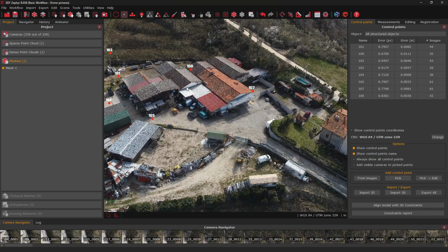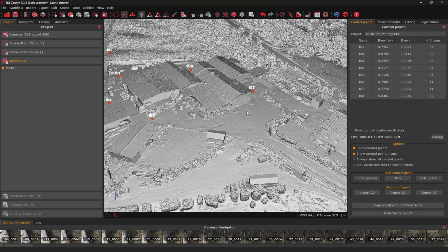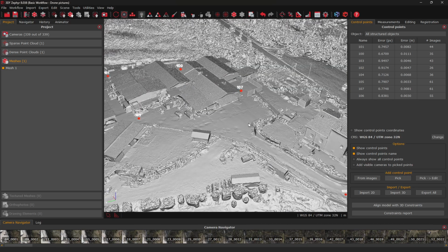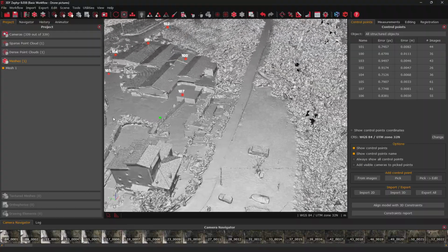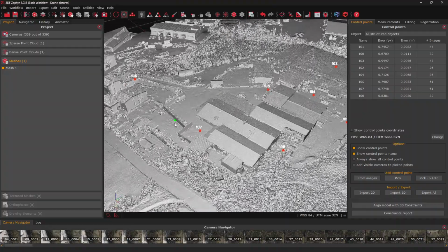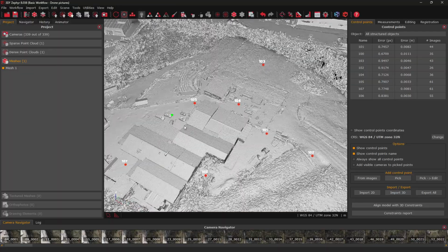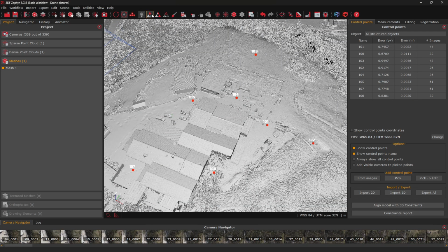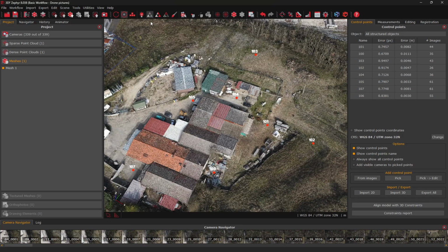To check the surface geometry details, enable lighting in the workspace using the icon in the menu bar, and then click the icon next to it to disable color and view only the surface geometry. Click the same two icons again to toggle back, re-enable color, and turn lighting off.